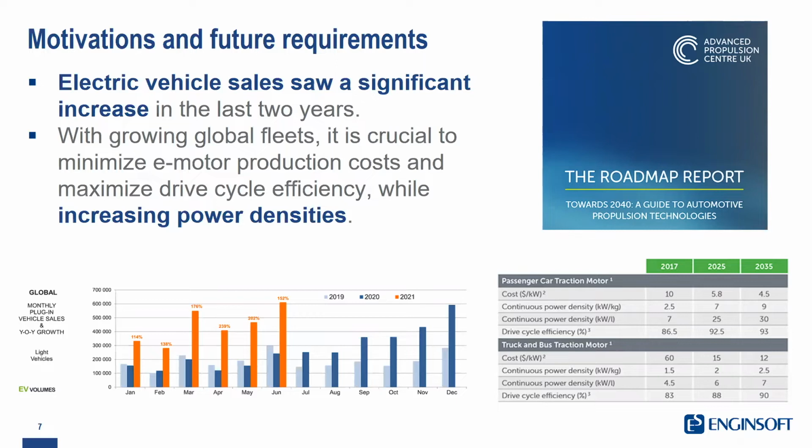So we are approaching a very important phase of the transition, and at the same time the projection for the power densities that the e-motor will need to satisfy, the efficiencies and the overall life cycle requirement, will need more power density. Moving from 2.5 kilowatt per kilo to 9 kilowatt per kilo, it's a lot of heat that needs to be removed, and conventional cooling methods like water jackets around the stator are not enough.